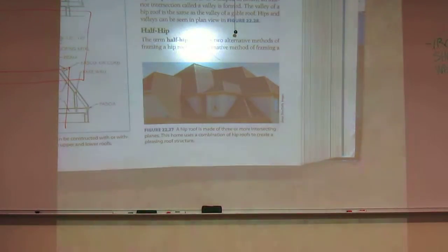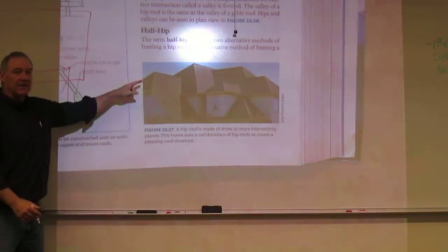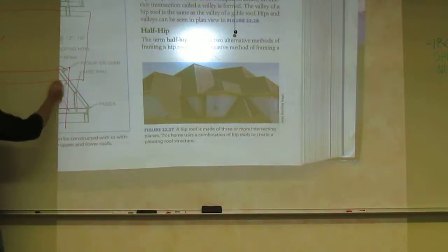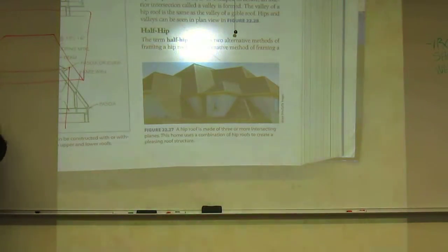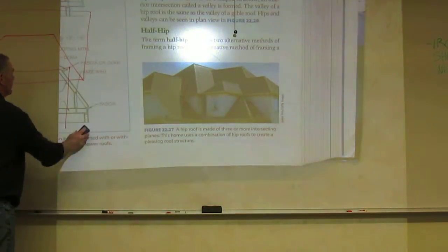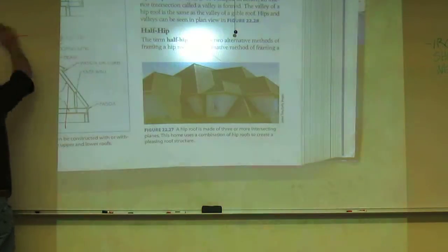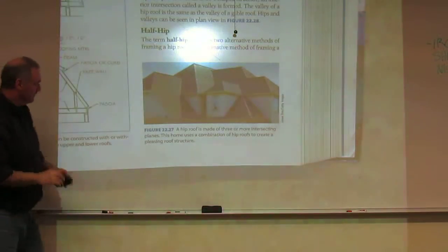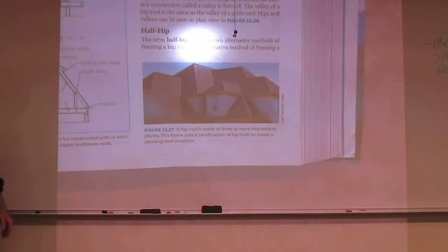So what people have started doing, now that we have truss companies, and certainly they built hips in the old days too, but it was pretty expensive, is a hip roof where we slope it both ways, and my roof looks like this for the same structure. So in essence, use hips to reduce the mass of the roof. That looks like a mess. That's too much going on top. That's a heck of a lot of stuff going on. Yeah, but it's real common in today's world to do that.